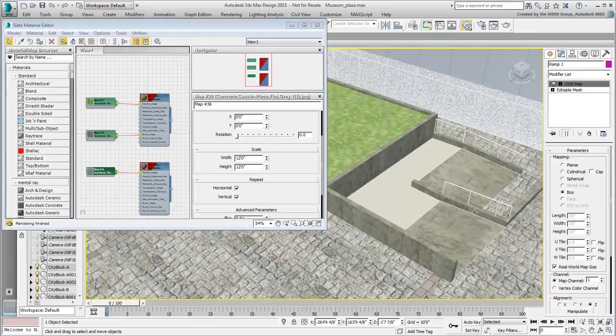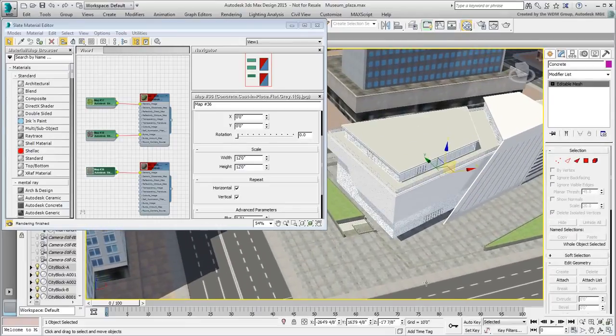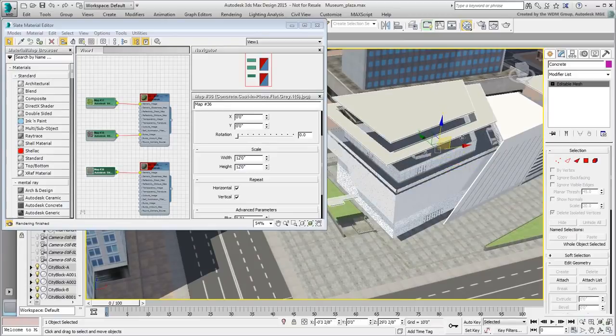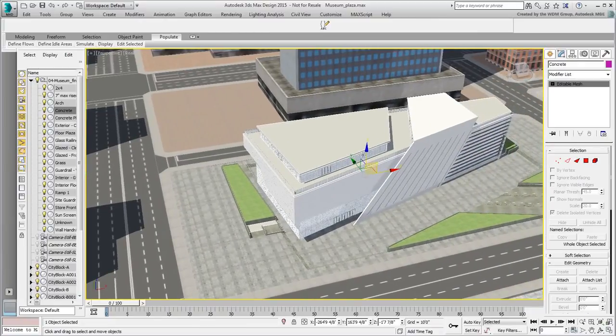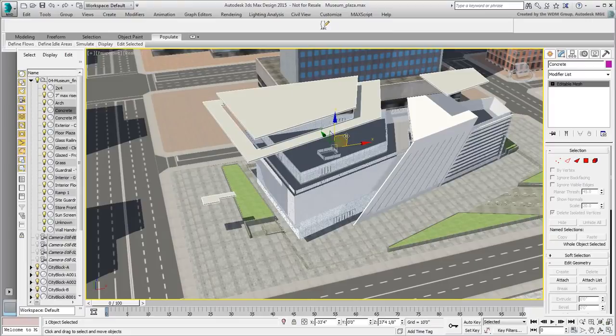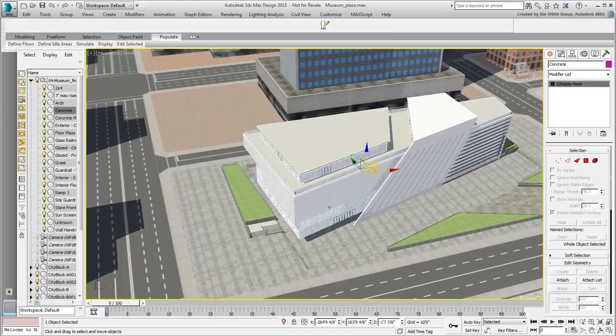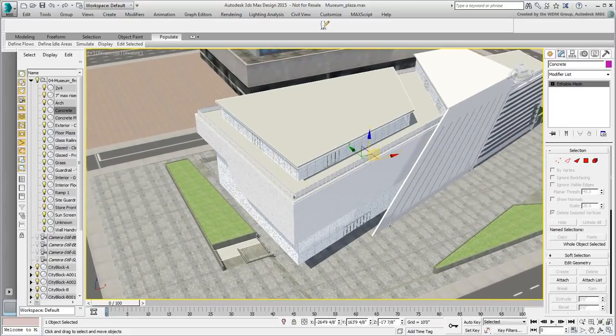Before you attempt applying the same material to the landings between the 2 ramps, consider that landing first. Select it and try to move it, and notice that it is part of the same object that also includes the top 2 floor slabs. This may have been done on purpose in Revit, or it may have been an oversight. At any rate, you can still use the same material you used earlier, or you can opt for a different one. You can also opt to separate the landing from the floor slabs, which is probably the safer option. That's the workflow you'll adopt.